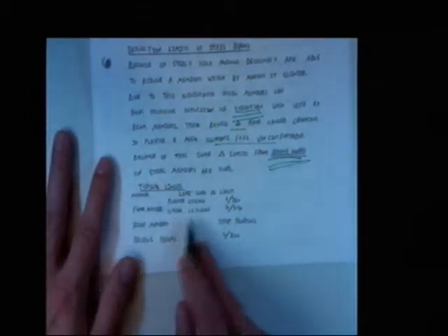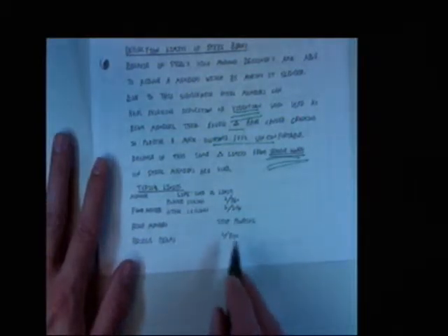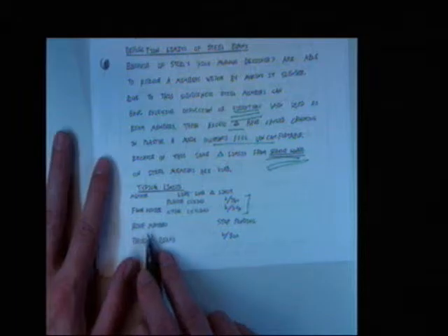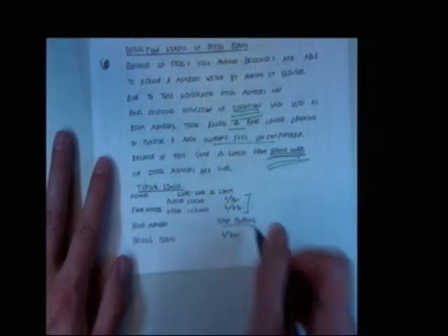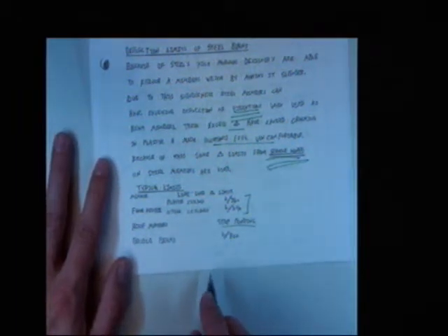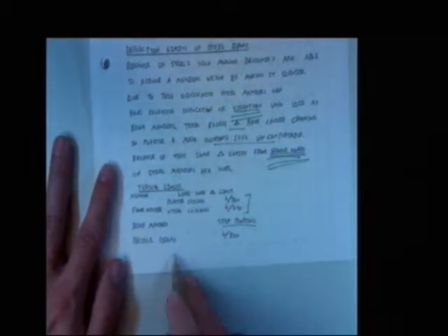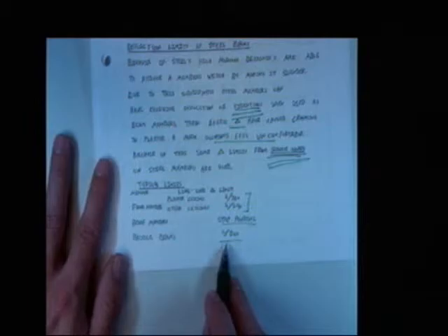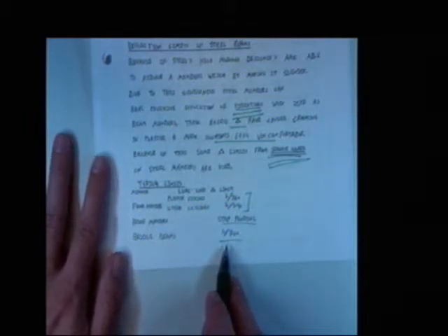But typical live load deflection limits, if you have a plaster ceiling, people think things like L over 360 or L over 240. These are common numbers. On a roof, you want no ponding to happen, right? In a bridge, you often have a much more stringent live load deflection limit. Surely at some point in your career you've heard about armies marching across a bridge and shaking it apart, right?